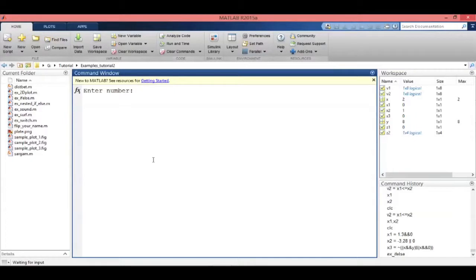So how do we input a complex number? We will enter the real part 2 and let's say plus. Now we have to input the imaginary part. In MATLAB, i and j represent imaginary numbers. Generally I prefer to write it as 1j star 3. So here the imaginary part is 3, and let's see what MATLAB gives us.